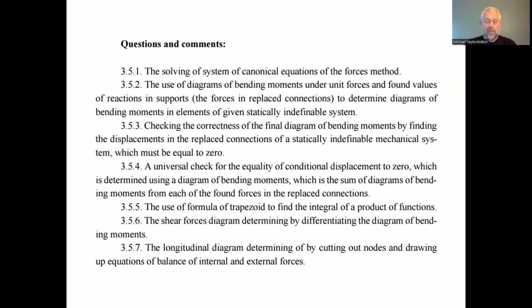And usually in the nodes of the mechanical system, we have the projections of the transverse force and longitudinal forces. Using the balance equation for the cut out nodes, considering the transverse forces, shearing forces, and the longitudinal forces, we can find the longitudinal forces. And the linear diagram of the longitudinal forces is just a line through the found magnitudes, the points of the magnitudes of the diagram of the longitudinal forces.